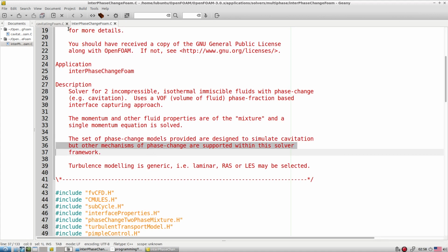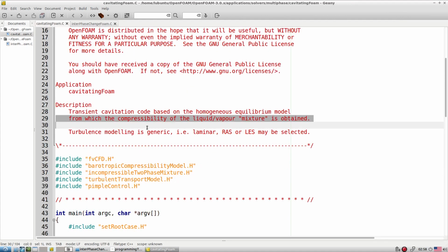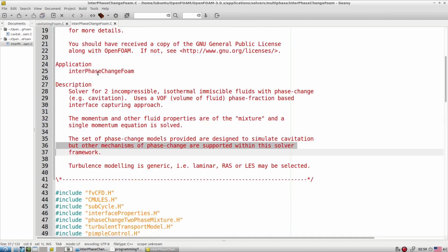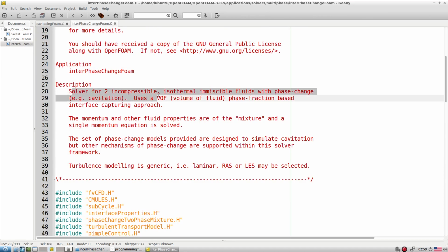What we are supposed to do is adapt the simple framework from cavitationFoam, remove the compressibility-based concept, and add this incompressible-based concept here, because this is for incompressible, isothermal, immiscible fluid. Whatever cavitation models are available inside this are for incompressible fluid. That is what we want, because we want to generate this cavitation foam for an incompressible class of liquid or fluid. So that is the idea.